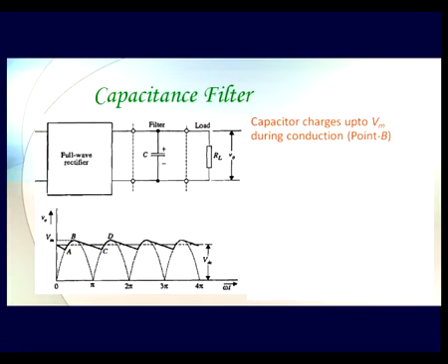And so the capacitor is able to give energy to the load when there is no input available from the rectifier output. So the capacitor gets discharged to, say, value C. But again when the next half cycle of the full wave rectifier comes, it gets charged also.